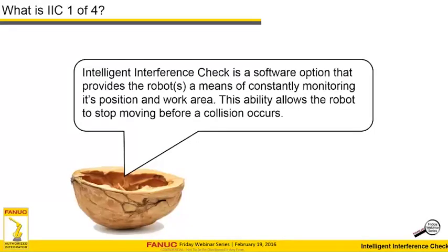So what is IIC? In a nutshell, Intelligent Interference Check is a software option that really gives the robot a way to monitor its position and its environment around it, so the robot can proactively prevent a collision from occurring.